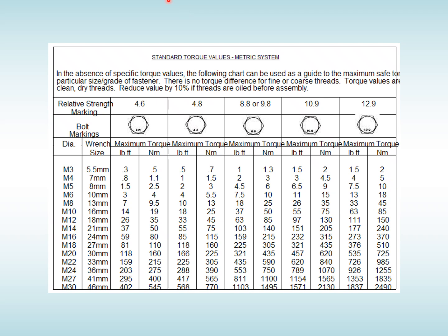Now, there's one thing to remember, and that is that if the threads are oiled or lubricated before assembly, you tend to reduce the value by 10%. Now, the reason that we torque the bolts is because if we under torque them, obviously they stand a chance of coming undone. If we over torque them, we'll take them beyond their point of elasticity and the bolt will stretch and it'll be no good.